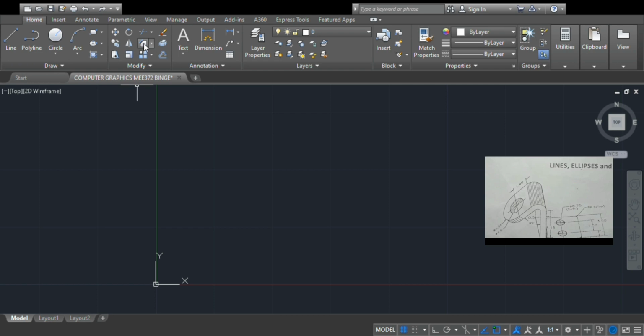We have different tools: polyline, arcs, spline, and fillets. Using fillet on AutoCAD is a little bit different from SolidWorks. If you just click the two lines, it won't work. You have to click the fillet option, then select the radius before making the actual fillet.